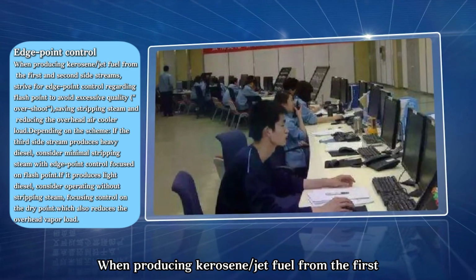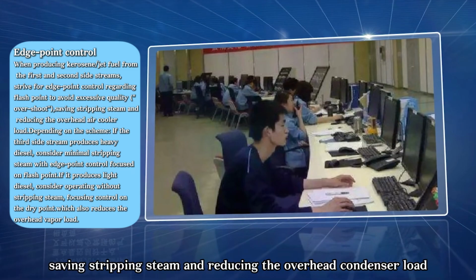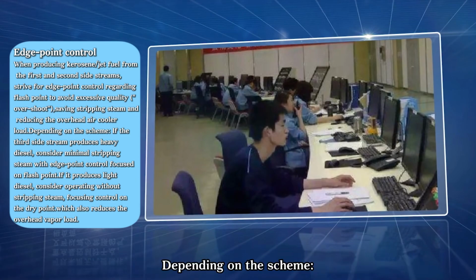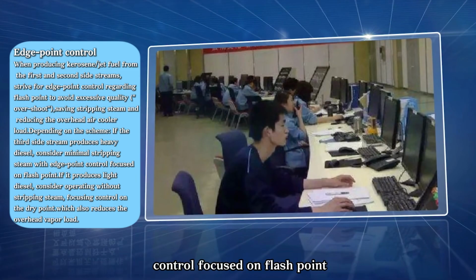When producing kerosene or jet fuel from the first and second side streams, strive for edge point control regarding flash point to avoid excessive quality overshoot, saving stripping steam and reducing the overhead condenser load. Depending on the scheme, if the third side stream produces heavy diesel, consider minimal stripping steam with edge point control focused on flash point. If it produces light diesel, consider operating without stripping steam, focusing control on the dry point, which also reduces the overhead vapor load.